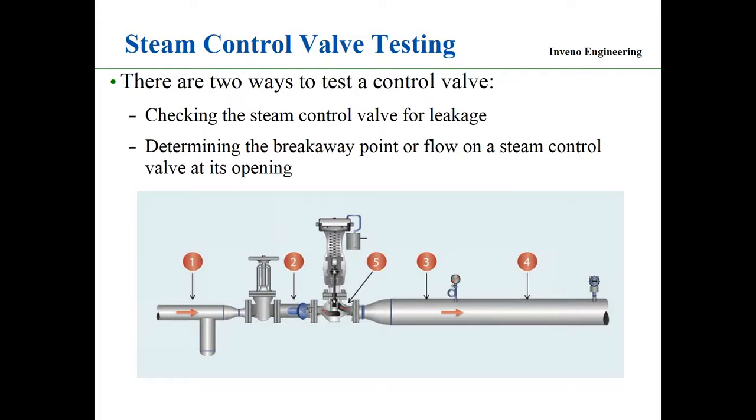The thing is, with no internal steam valve leakage, we don't have to worry about premature valve failure, because steam leaking through a valve will wire draw the seat area and the valve mechanism, the plug or whatever. The other thing is that we are looking at no component failures within 6 years of installation, period. The steam system, we cannot accept today component failures within 6 years. And internal leakage can cause issues in operation. So by doing this test, then we can determine what's causing it.